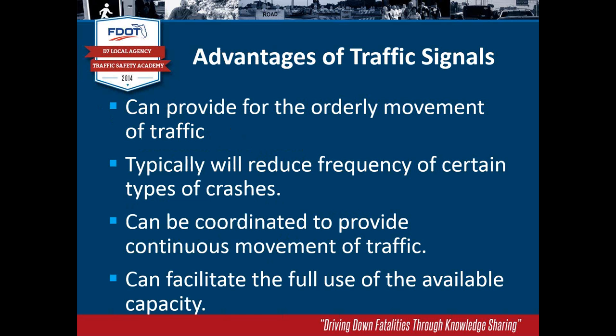Some of the advantages of traffic signals: they can provide for the orderly movement of traffic, and typically they will reduce frequency of certain types of crashes. Right angle collisions in particular, signals should reduce the frequency of those types of crashes. They can be coordinated to provide continuous movement of traffic, as I was talking about, and they can facilitate the full use of the available capacity. Now you'll see I used a lot of words that are kind of loosey-goosey, if you will.